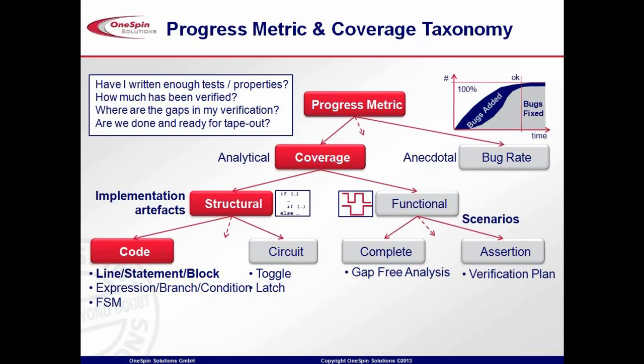So you heard a few words about gap-free verification. If you really want to prove 100% functional verification of your design, your IP, you can go for gap-free analysis, which really guides you on how to verify the functionality of your design and when you're done. But today, the rest of the slides will really focus on answering the question, have we written enough tests, and all the other questions we've heard today. So the focus will be code coverage, mainly line, statement or blocks.